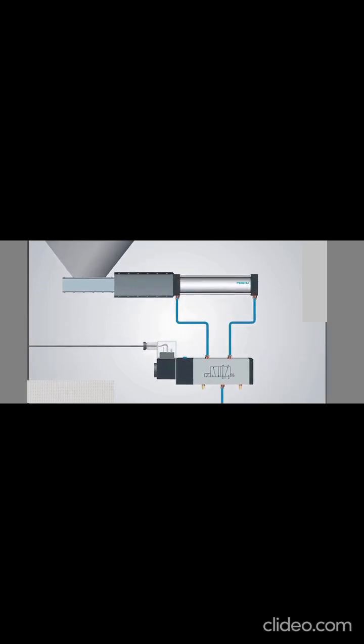A double-acting cylinder has an air chamber on each side of it to move the piston back and forth. One of the directions expands the cylinder and closes the slide gate valve to block the material coming out of the silo. And the other direction retracts the cylinder to its first position. Therefore, the slide gate valve is a normally closed valve. Meanwhile, the sound you hear is the air inside the cylinder exhausting from the valve into the atmosphere.